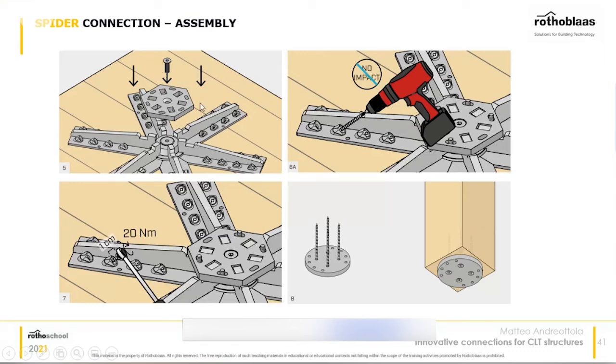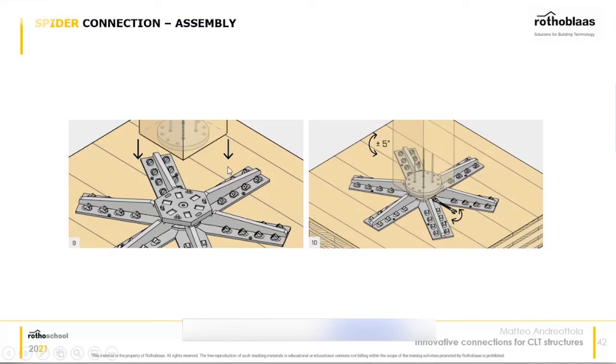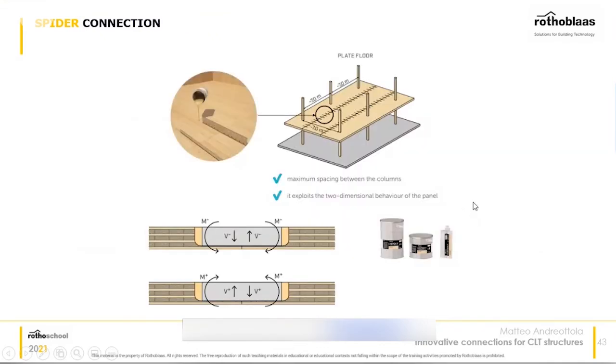And this is how you put together this connection. It is actually very easy, and you can use timber columns, or you can choose to have a hybrid structure and use, for example, steel columns or other materials as well, like aluminum, for example. In order to, of course, create a continuous slab, it is important as well to have this moment connection and create really this continuous slab.